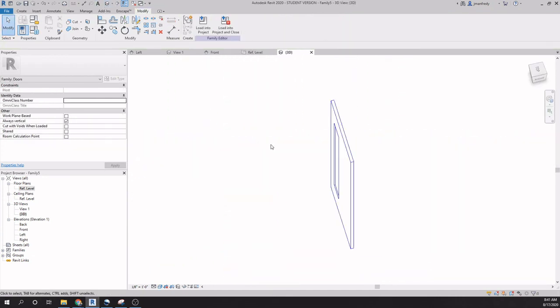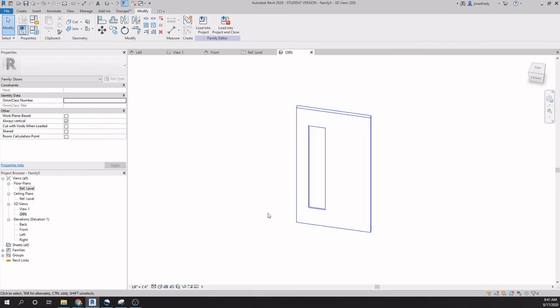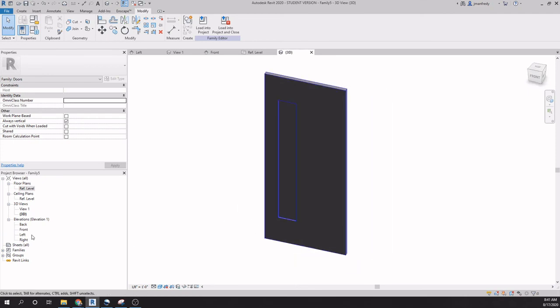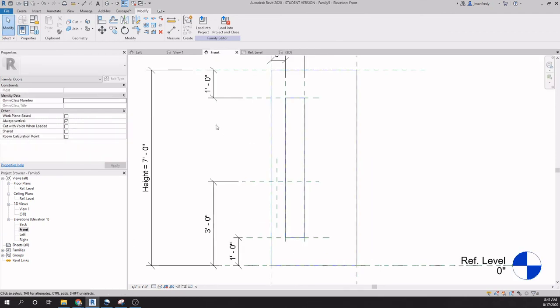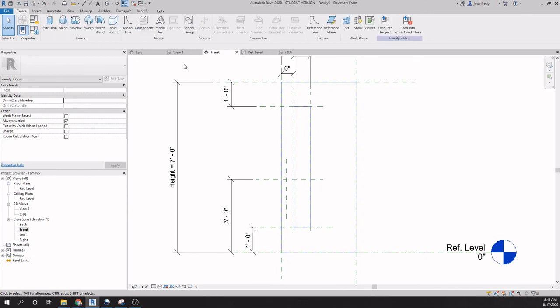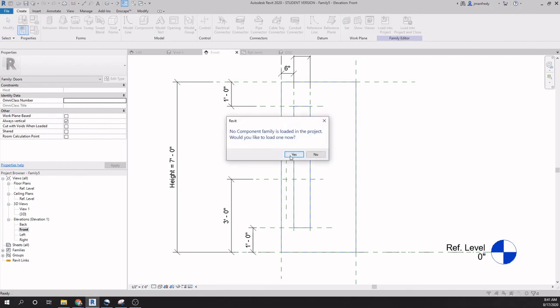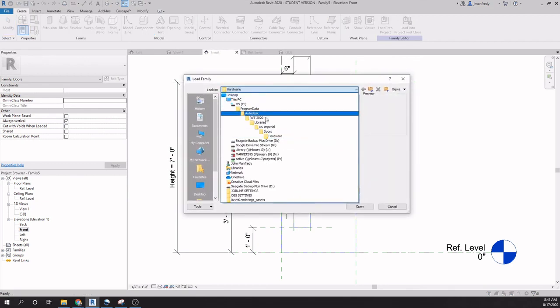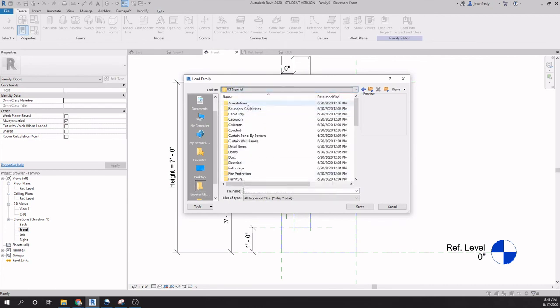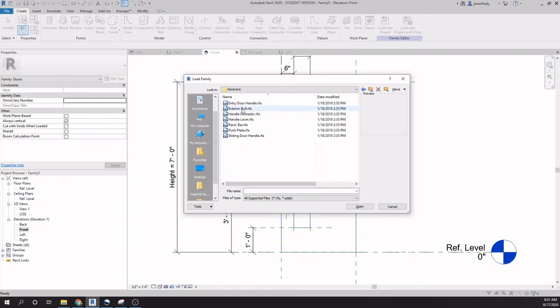Now, there's my door. And the side light is right here. If I go to shaded view, it's solid currently. There's no material assigned. In the front view, quickly, I want to add a little handle. So I go into Create, and I know Revit has handles. Under Components, I can load a component, and in the Door Family folder, right? These are all my families here. So my directories. Here's Door and Hardware.